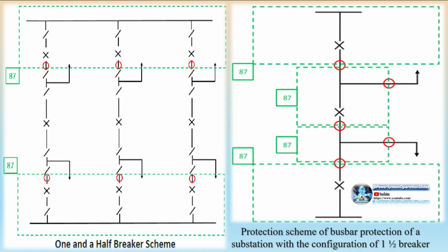In a low-impedance scheme, an open or shorted CT produces a differential current proportional to the load current on the faulty circuit. Settings can eliminate differential current under normal load conditions, allowing a sensitive threshold to detect an open or shorted CT. This threshold can trigger an alarm, disable the busbar protection, or trip the bus. A more sophisticated method detects changes in differential and restraint currents, where the loss of CT output increases differential current and decreases restraint current. Arc protection, light sensitive.